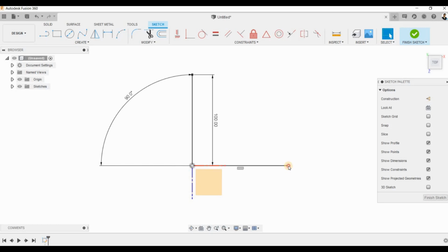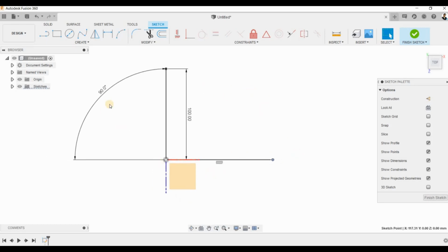Here again, if I drag this, you can see that it is able to move. So my sketch is not fully constrained. What I mean to say is it's not fully defined. Let us say you're trying to draw this using a pencil and scale. Without specifying this dimension, you will not be able to draw it accurately. A person might draw it like this and another might draw it by dragging it or with a smaller dimension.